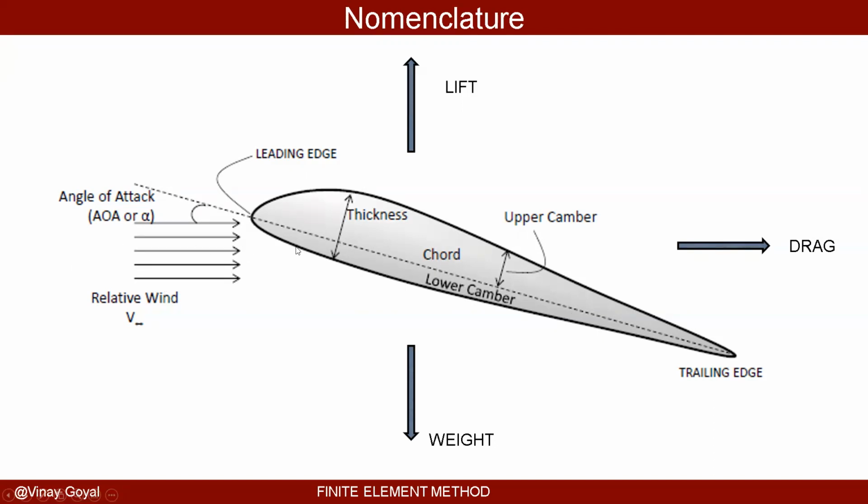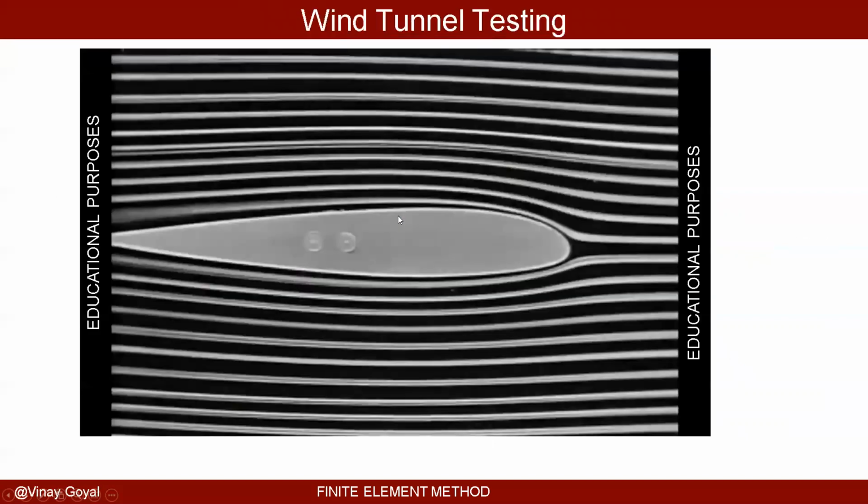That angle is going to change the amount of lift. So if you have more angle of attack, more lift will occur. If you have less angle of attack, less lift will occur. There is an angle, however, at which, if it reaches a very high angle of attack, in that case you start to lose all the lift and you stall. But typically, these are the loading conditions acting on the vehicle.